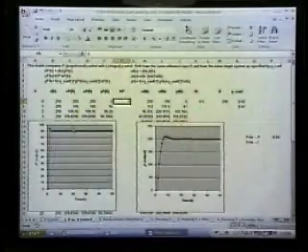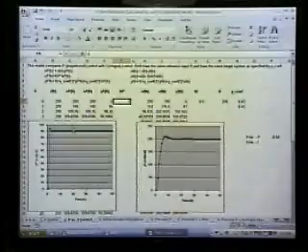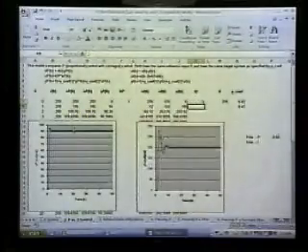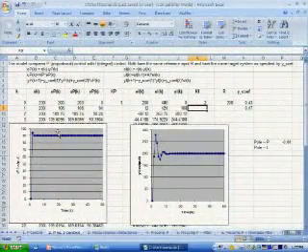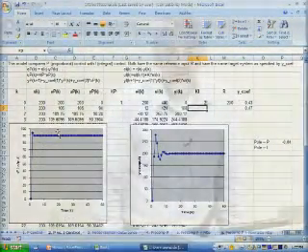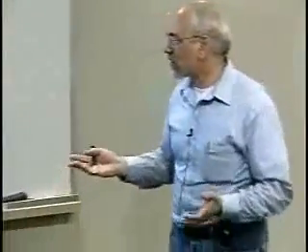That's pretty cool. So what happens if we change that? How about if it's, I don't know, 2? Wow, converges there too. Okay, this is actually a property of the integral controller, a very important property. And I'll show you why. It actually falls out of the analysis, and I'll show you why in a second based on the theory that you already have. But what we do notice is that it's not as fast as a proportional controller.